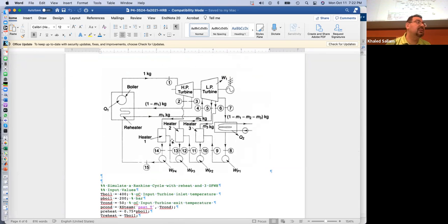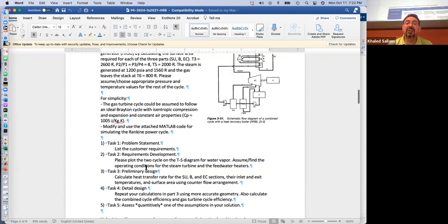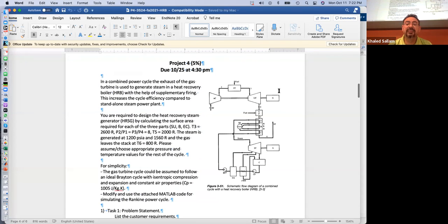So with even 7 feed water heaters and a reheater and a superheater and all those things, what is the efficiency going to be? What do you think the efficiency of a steam power plant would be? And let's go supercritical and everything. We are talking 40, right? Pushing 40. We're going to be 40. But you put a gas turbine on top, and we are talking 65. So we go from 40 to 65.